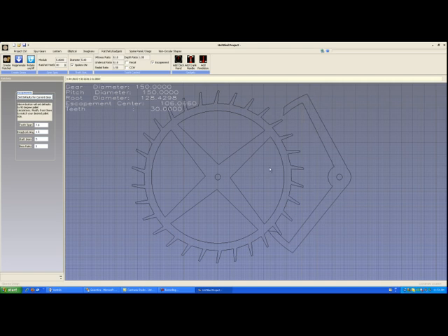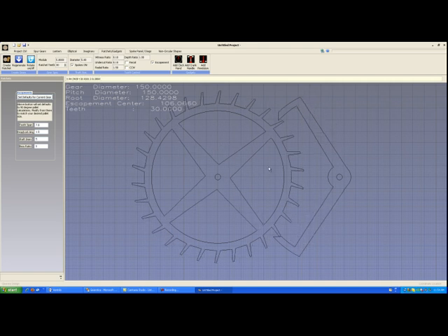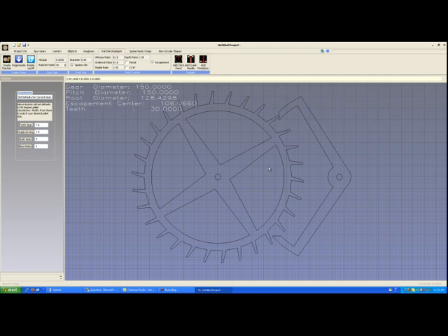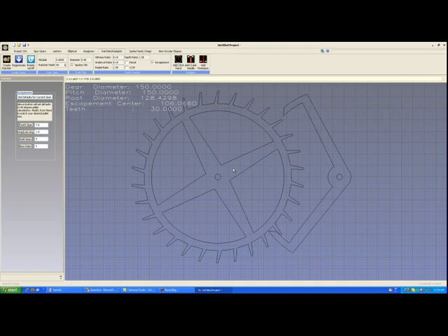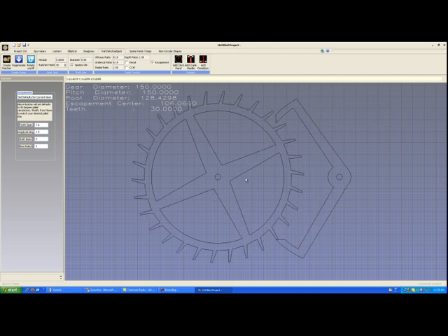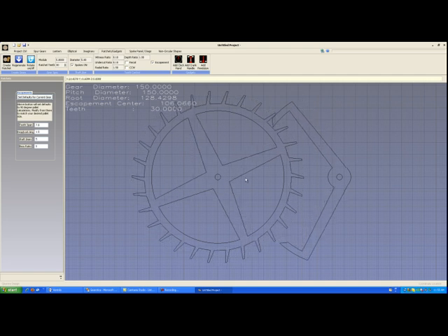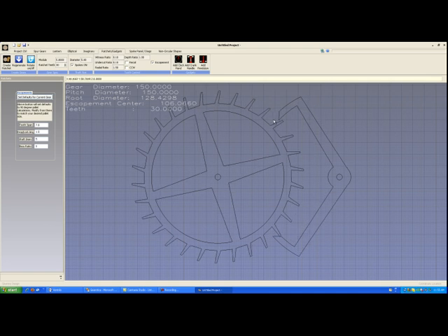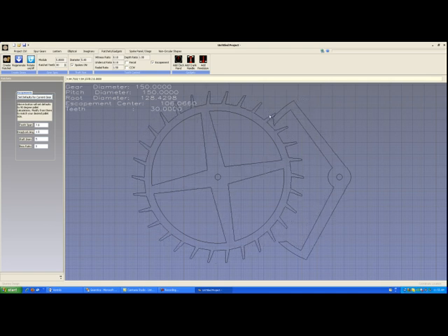The key to an escapement, which is called an escapement incidentally because it allows energy to slowly escape at a measured rate. Consider that this deadbeat gear has a tendency to go clockwise. In other words, there is a spring or a weight or something which is forcing this deadbeat gear to turn clockwise. As you can see, if we look at the top, as it rotates, the tooth will come into contact with the pawl on its lock face.